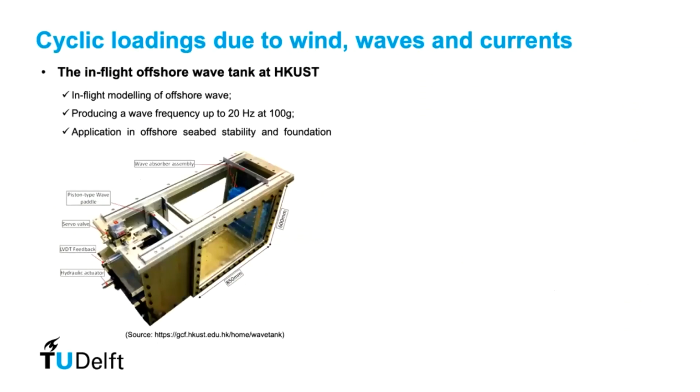Another type of model that can be developed for studying the interaction of loads with infrastructure is, for example, this wave tank. This wave tank is something similar to what you will find in hydraulic engineering. And at the end, we are all engineers, so we take inspiration from good examples in other areas. What you see here is a plunger that moves sideways, and by that motion, it pushes water sideways. Therefore, you can install a given infrastructure, a wall, a quay wall, or a foundation over an erodible sand layer and explore the effect of this waving mechanism on the soil fluid structure interaction.